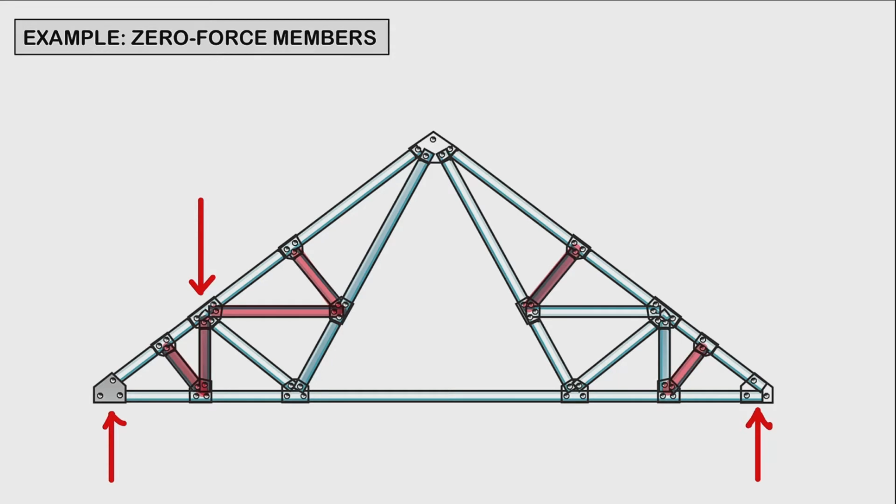All right. So two collinear members again, no external loads, no support reactions. This one is a zero force member, so we could disregard that. Therefore, this member is also a zero force member. All right. So what else? We could look at this joint. Two collinear members. This is a zero force member, so we could disregard that. Therefore, this member is also going to be a zero force member. So let's highlight that again.